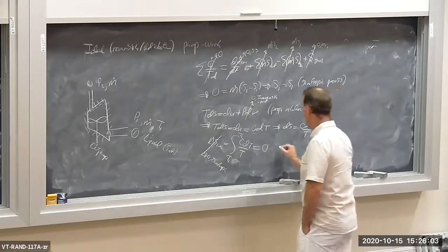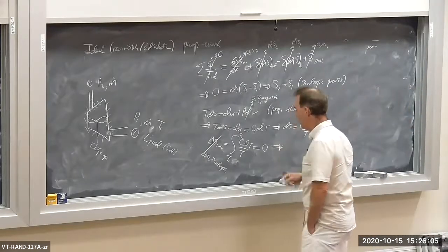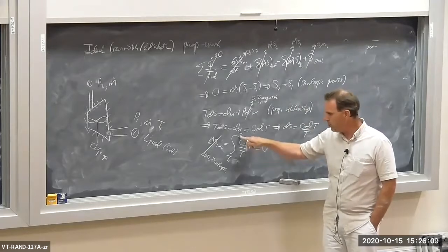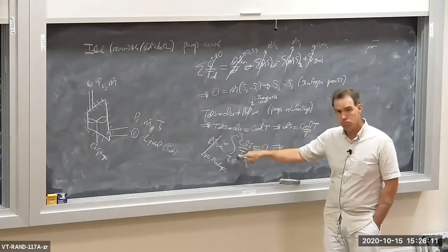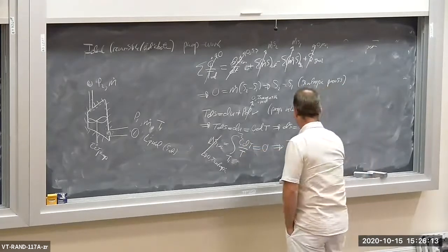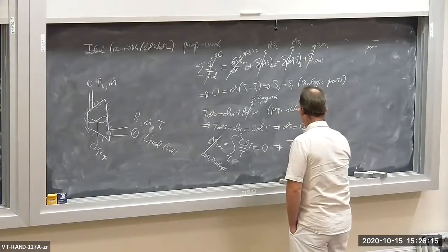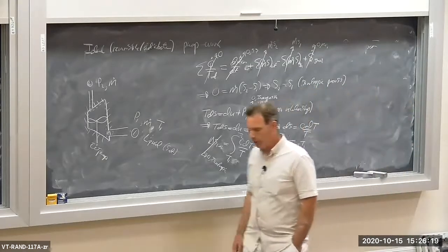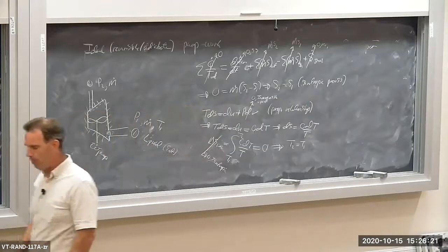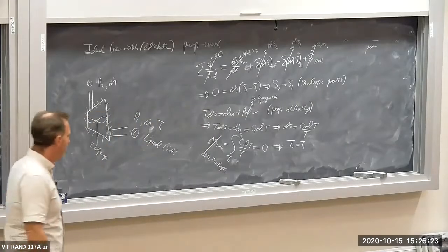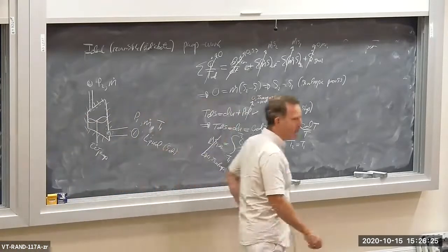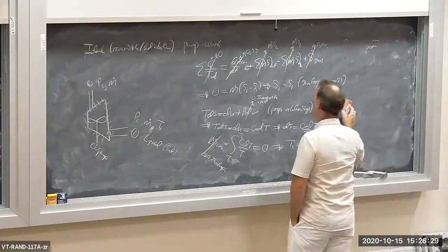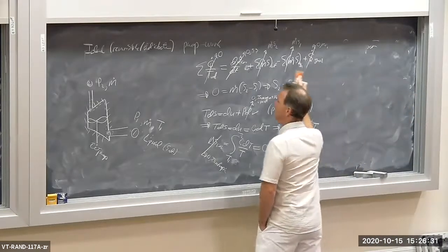Therefore, getting a little cluttered here, but try to follow along. If this integral is 0, it means that this temperature change is 0. That means T2 is equal to T1. So for adiabatic reversible pump work, there is no temperature change from the inlet to the outlet. So isentropic process.